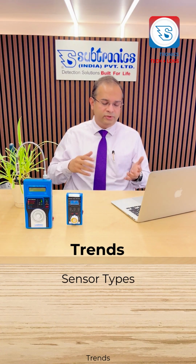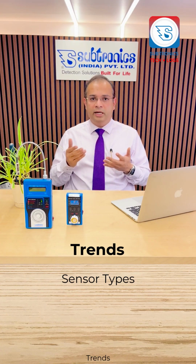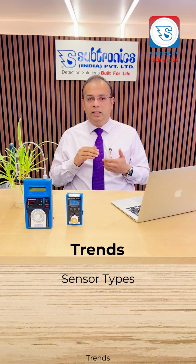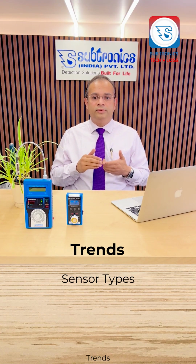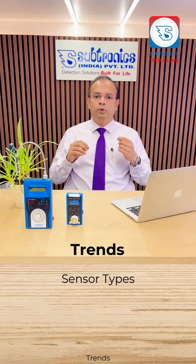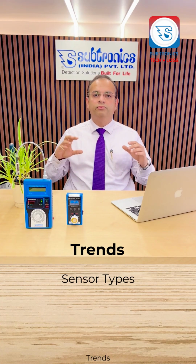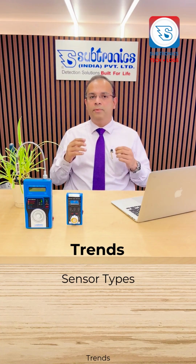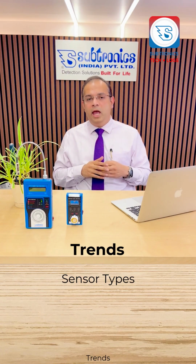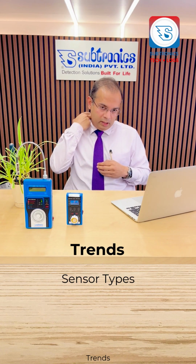There are different types of sensors: semiconductor, electrochemical, Pellistor based catalytic bead type sensors. There are NDIR based sensors. There is something the latest which is TDLAS. Now these stand for tunable diode laser sensors. Now these are all trending sensors, and we work with most of these sensors depending on the type of gas that you require, the type of range that you require for these gases and the type of alarm levels you require.